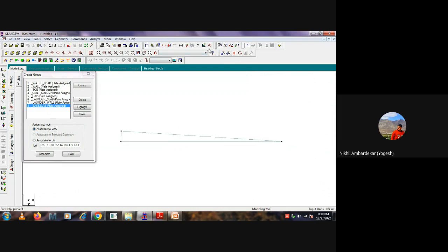If I check its dimension, what is the width? 0.03 meter, as against the length of that plate, 0.47. Because of that, STAAD is saying that the aspect ratio for this plate is not good. That will be only a warning, so we can ignore that. Because of that, if we check wrap plate, we will have some numbers there.